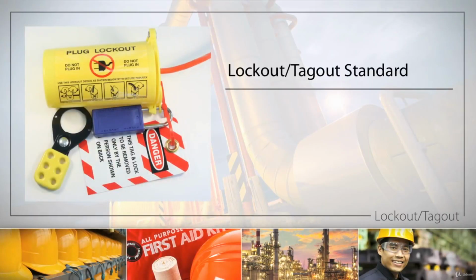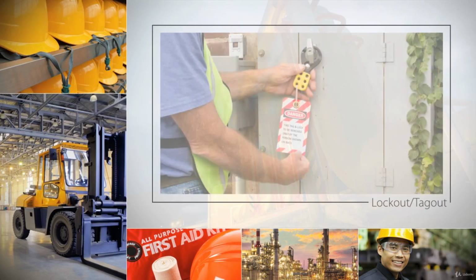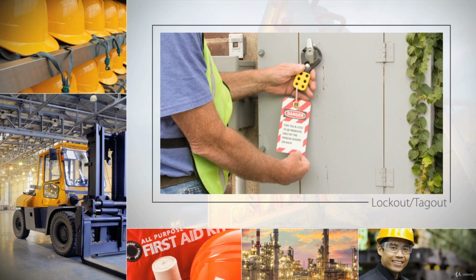Three types of employees are covered by OSHA's lockout-tagout standard: authorized, affected, and other. The amount and type of training that employees receive depends on their job in relation to the machine that is being locked out or tagged out. Employees who are authorized to execute the actual lockout, tagout of equipment and perform the servicing or maintenance on that equipment must receive training in the recognition of all applicable hazardous energy sources: electrical, mechanical, hydraulic, pneumatic, and chemical, necessary for controlling and isolating the energy source.